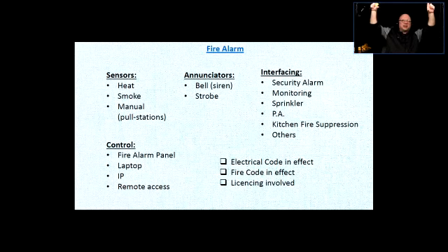They just sit there, right? And there could be some other sensors there. So if there's a fire, there's a sensor, usually a piece of PVC or a specific material that can withstand the heat of normal operation of the kitchen station. But if the temperature goes too hot, if there's a fire, that thing is going to break, and the spring-loaded action is going to release some triggers, and then a system with fire suppression chemicals is going to release them through those nozzles to suppress the fire, right?